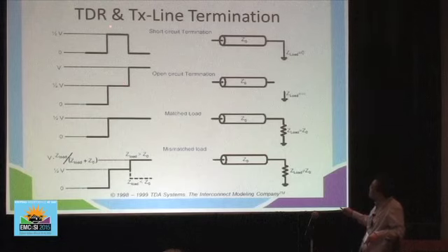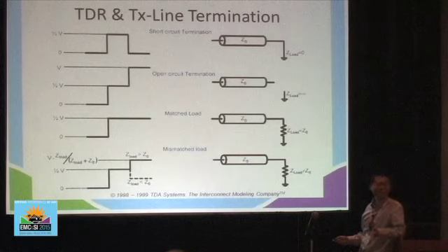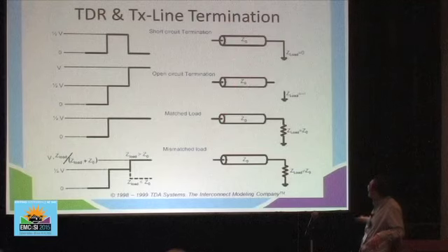So here, at t equal to 0, it jumps to a certain voltage. Okay, we notice if the voltage is half of the source voltage, then immediately we know the characteristic impedance is the same as the instrument impedance, 50 ohm. Only when the two impedances are 50 ohm do you get half of the source voltage, okay? So that means all these Z0s are 50 ohms, okay?